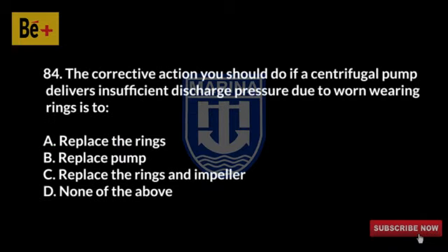The corrective action you should do if a centrifugal pump delivers insufficient discharge pressure due to worn wearing rings is to A. Replace the rings. B. Replace pump. C. Replace the rings and impeller. D. None of the above. The answer is A. Replace the rings.